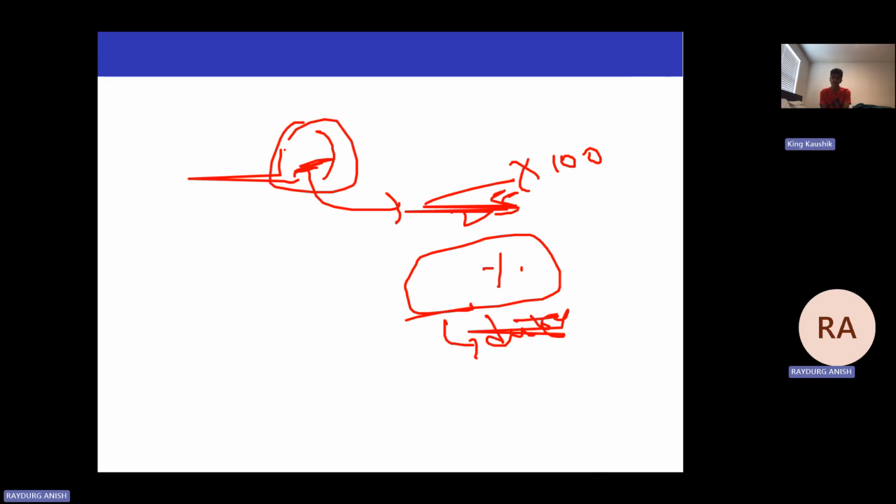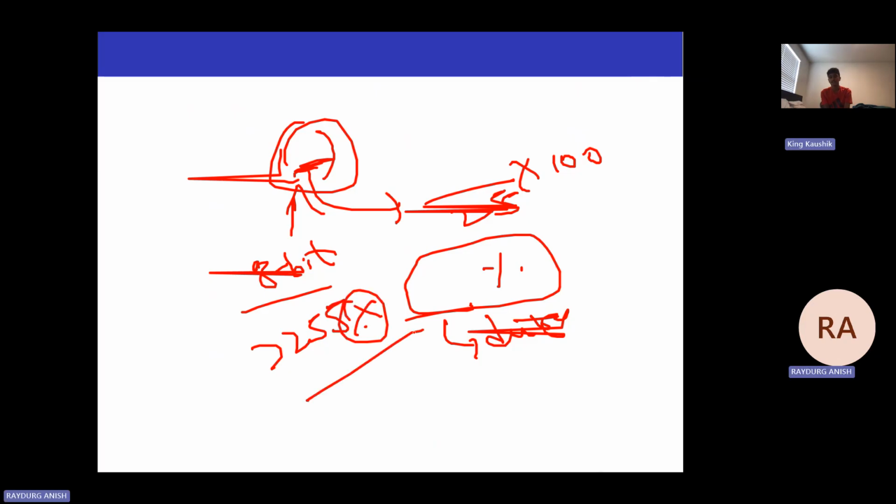Whatever value we are giving internally, it is 8-bit, so you cannot give more than 255. What happens if I give more than 255? It simply throws you an error in the code. You cannot compile and dump it in the board.